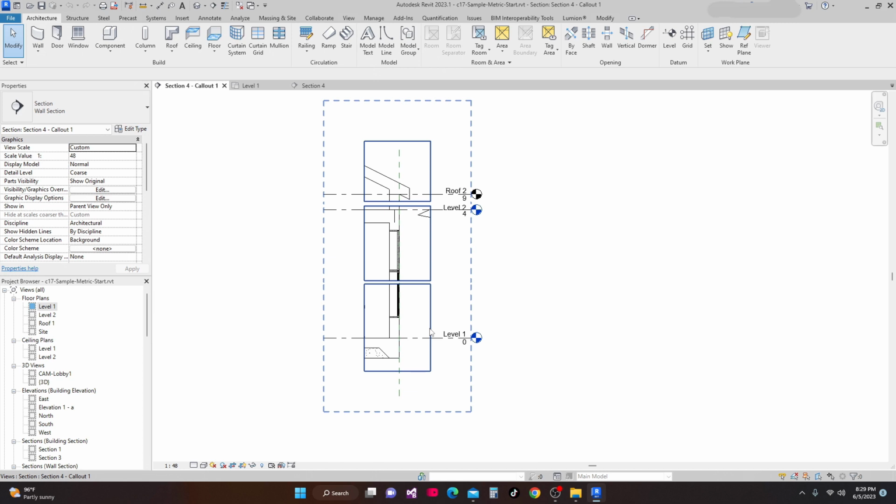And what is the meaning of model detailing? Model detailing is a process of creating detailed drawings directly from the 3D model. Once you become familiar with creating families and customizing your project templates, the approach we refer to as model detailing still involves the use of some detail components.